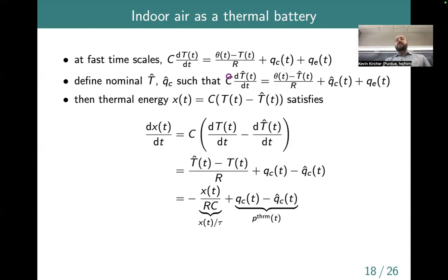And then we're thinking that, well, the real T, the true T up here, maybe it deviates from that T hat in some way. We're a little hotter at sometimes, a little colder at other times. And then the real QC would also deviate from this Q hat, the nominal one. So there's a move that I'm doing here, which is called defining a perturbation system. You define some nominal operating point, and then you look only at wiggles away from that operating point. And that's a super common move in control systems, when you're linearizing systems about some operating point, things like that. So as you take 365, 375, probably you'll see stuff like this again in linearization sections.